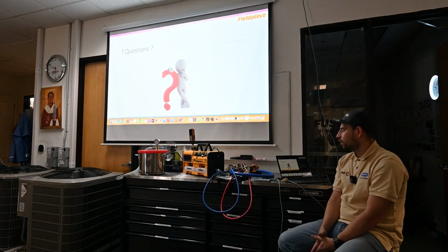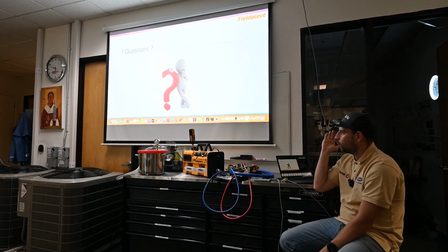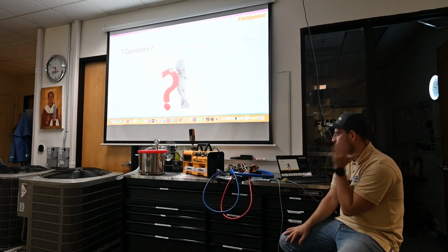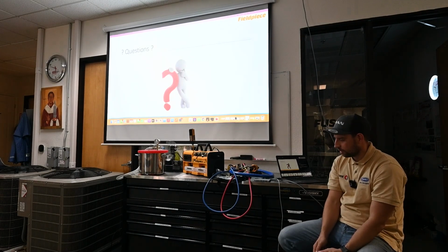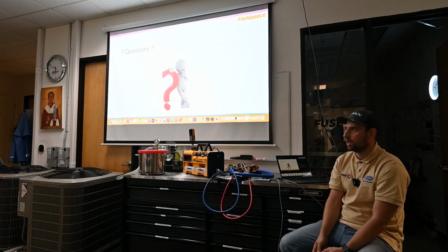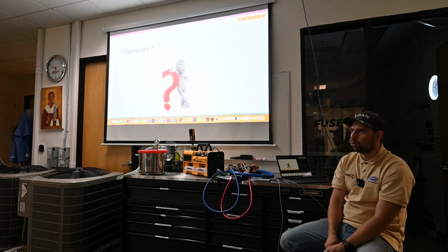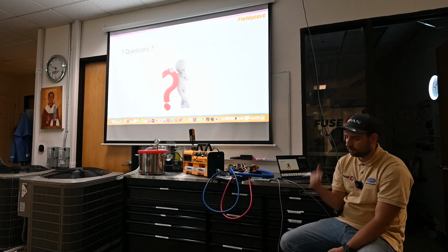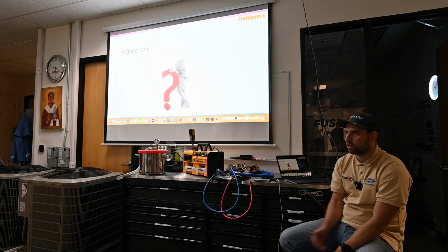For vacuum, we need to have a vacuum machine, vacuum gauges, hoses, and a vacuum hose removal tool. That's it. In my practice, when I finished repairing some systems which had a leak, sometimes the vacuum time was more than half an hour, and if the vacuum is very slow, what I usually did, the first time, I try replacing the oil.